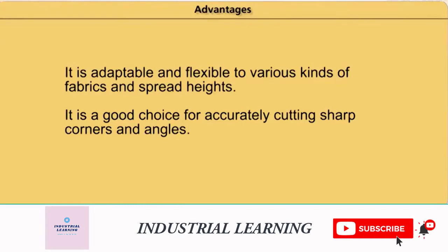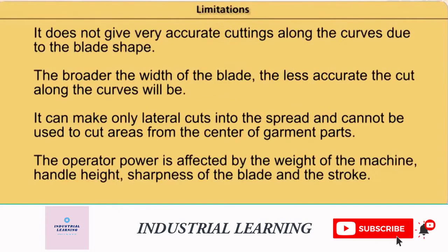Advantages of the straight knife. This machine is most commonly used in the industry today because of its adaptability and flexibility to various kinds of fabrics and spread heights. Due to the shape of the cutting knife, it is a good choice for accurately cutting sharp corners and angles.